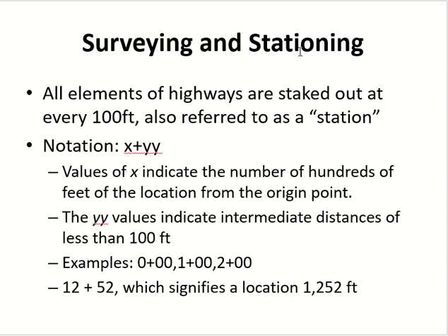So if you crossed 100 feet, then it is one station. So before the plus sign, 1. If you crossed 1000 feet, then you crossed how many stations? 10. So number before the plus sign is 10, okay, and whatever is left is after the plus sign, okay. So you crossed a distance of 110 feet, so you crossed one station, 100 feet, and then 10 feet more, right? So 10 will come after the plus sign, okay. So something like this.